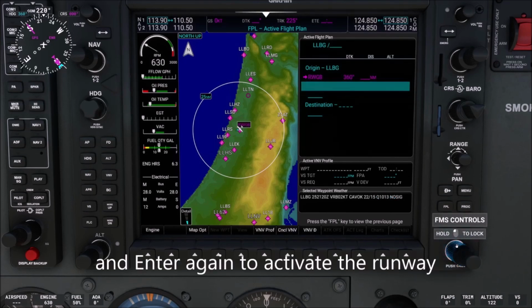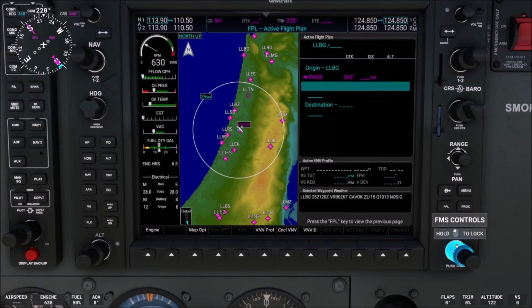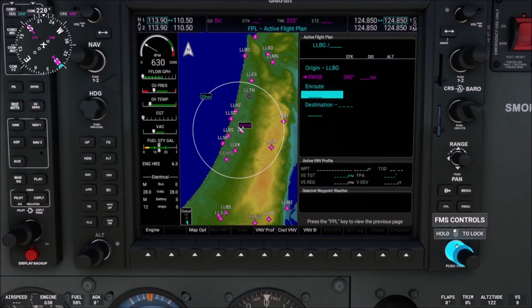Excellent. And the route is blinking. Inner knob, the big knob, one position down. That's all. I could as well stop the clip here, and I'm sure that Jonas knows what to do now. Okay, so waypoints. It shows a few waypoints. I suppose we will continue from Tel Aviv. So this is just an example, okay? You can have your own waypoints, whatever you want.